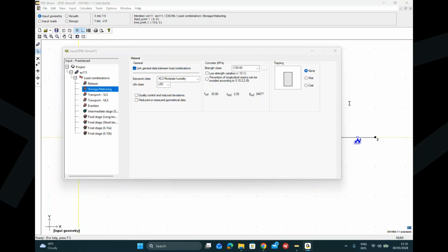Is it possible to change the stirrup type to get more legs per stirrup? Yes. So keep in mind that this calculation is made in the case of stirrups. So the shear plane intersects a number of legs for a certain distance. In this case, if you apply a load close to the support, it will be the distance between the support and the applied load.